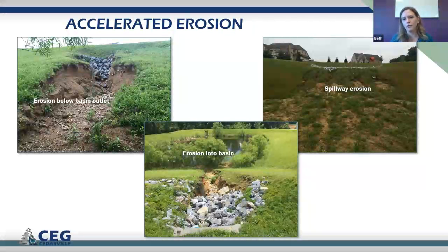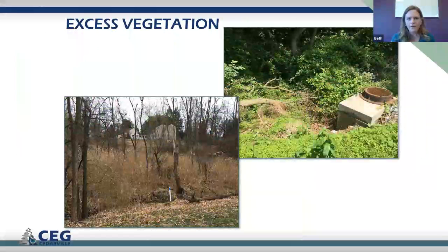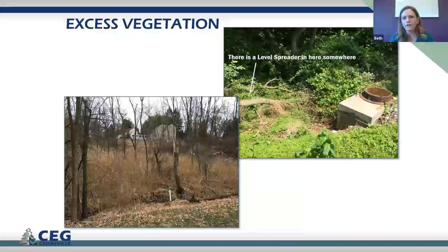It looks like it is actively eroding, but say it was completely covered with grass. Just to repair the rill, it's not worth the amount of disturbance. Going in with a piece of equipment would cause you to regrade that area and restabilize it. So there should be kind of a common sense approach to these violations.